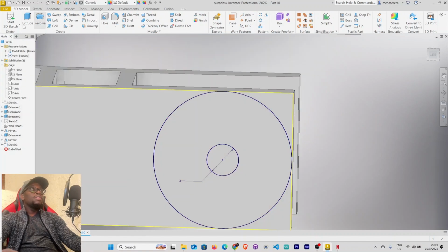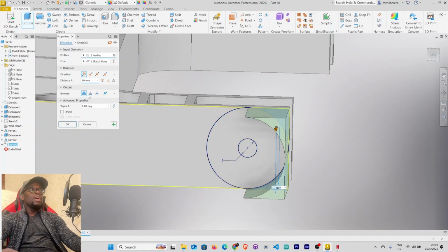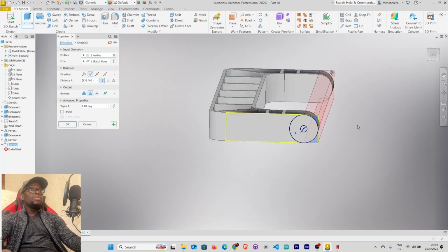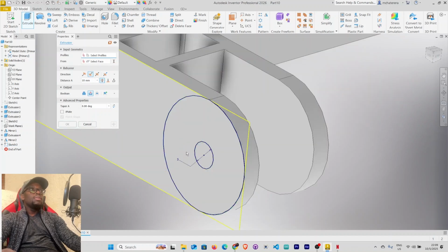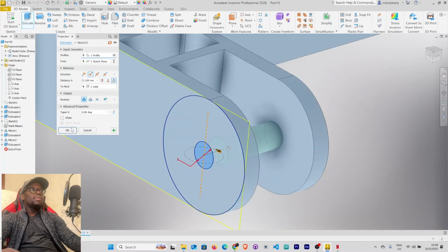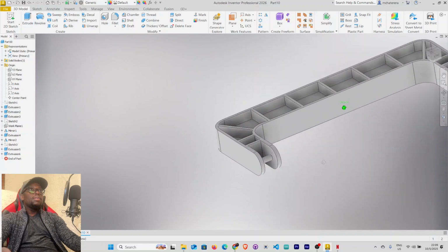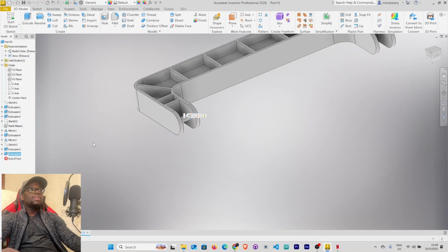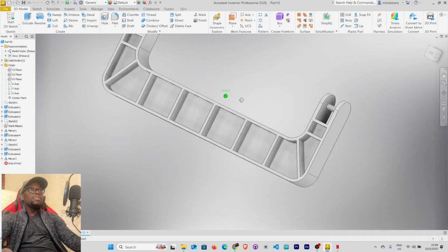Now let's extrude this. Extrude this profile and this one. We are cutting through all, so you can see the profile. Let's chain our extrusions. Click the plus icon. Now let's add this profile. We are joining, and to next. Click OK. So done here. Let's mirror our last extrusion, this one here. Select the mirror 2, and our mirror plane is the YZ plane. Click OK. So there we go.